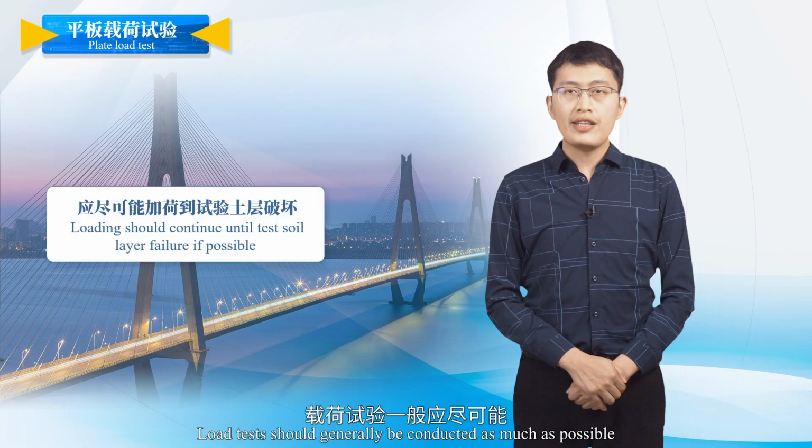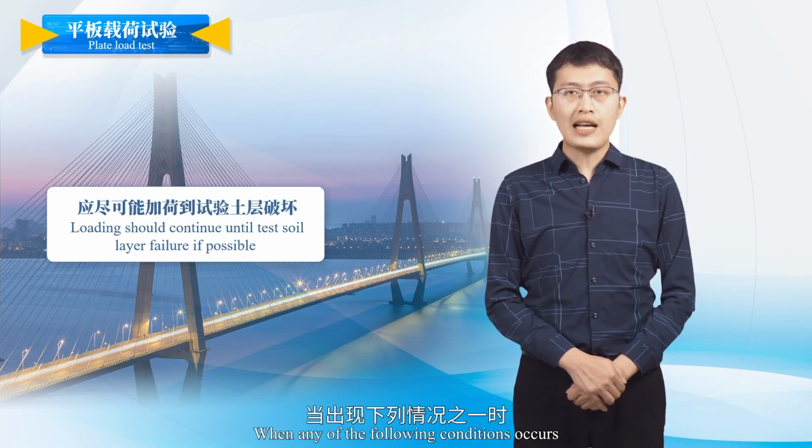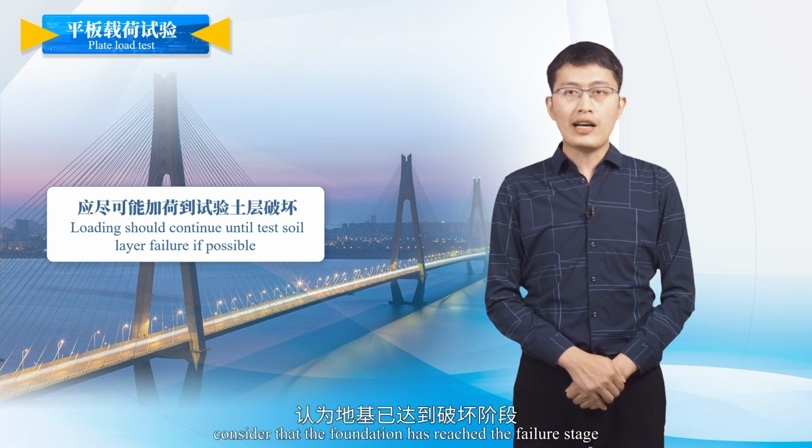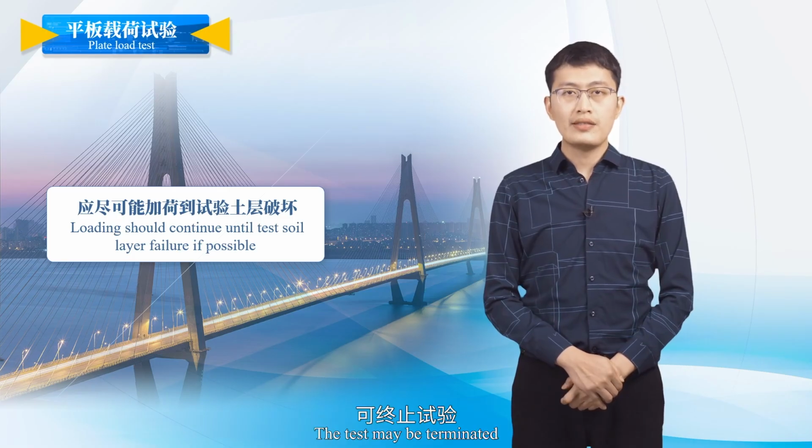Load tests should generally be conducted as much as possible, loading until the test soil layer fails. Then terminate the test when any of the following conditions occurs. Consider that the foundation has reached the failure stage. The test may be terminated.